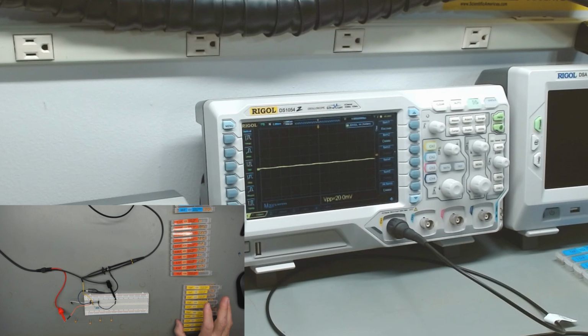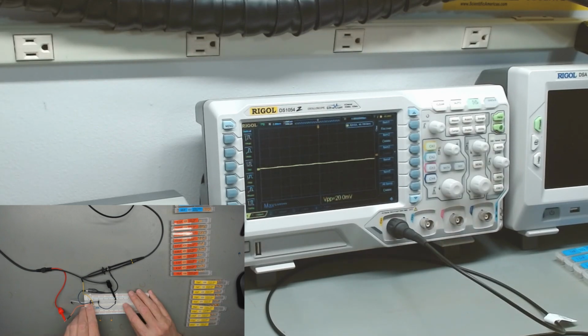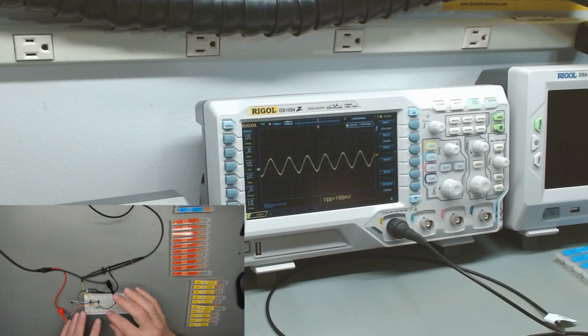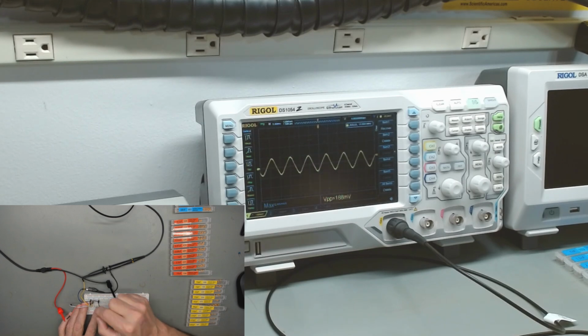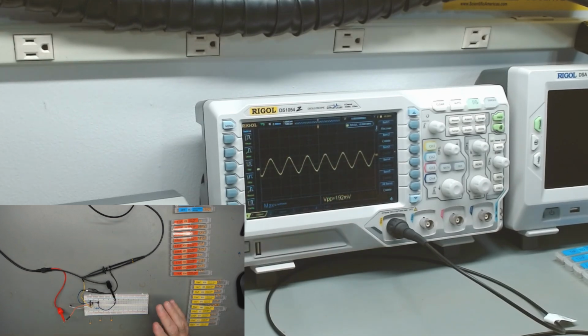Let's look at what happens with our signal passing an AC signal through different capacitors. So I'm going to go ahead and plug in this 10 microfarad. You'll see we're getting 188, 190 millivolt peak to peak. If I move my scope over to the input, you'll see that that's basically what we're putting in. So that 10 microfarad capacitor is having almost no effect on the signal strength. But if I pull this out, remember it had almost no insertion loss through this capacitor. There was no losses, okay?